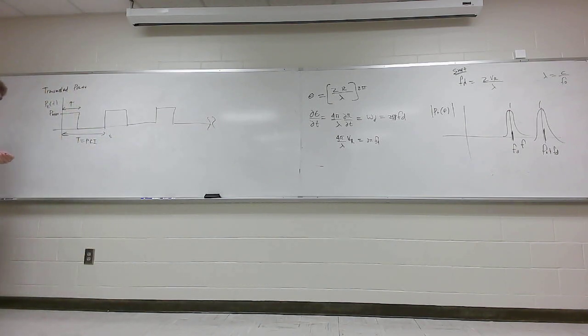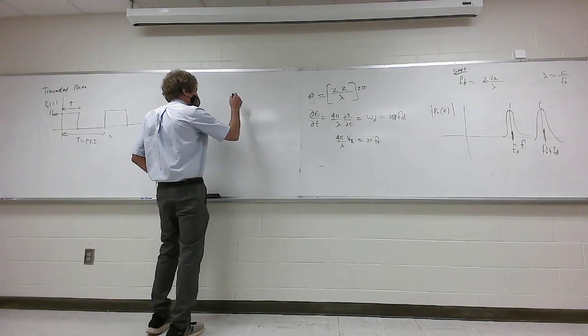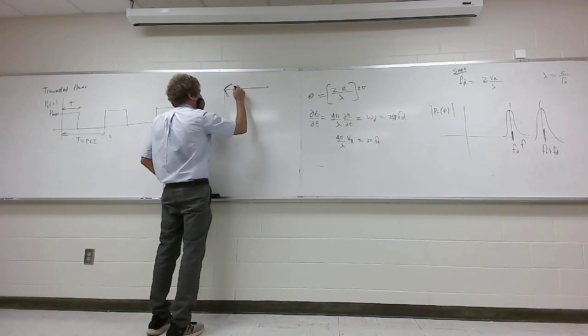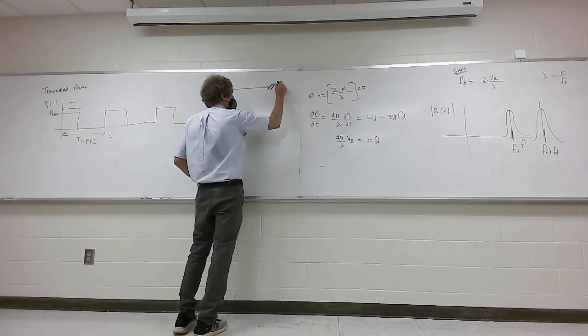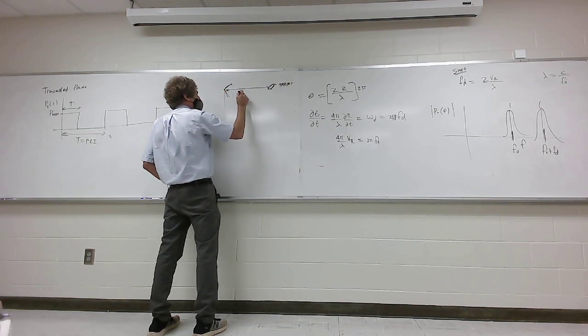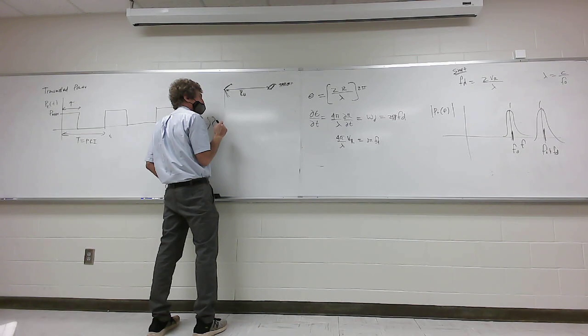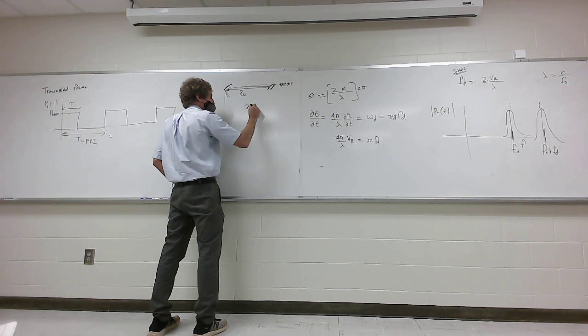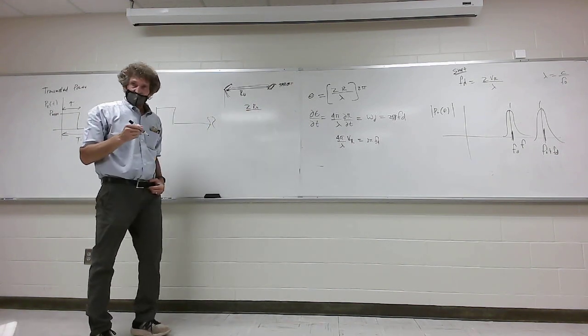Now, there's more to this, but in a nutshell, when we take a look at the maximum distance that we can discern unambiguously, the way we get it is this. Well, this is my radar here, and here's the target. And this we're going to call the maximum unambiguous range. Well, I know the signal goes out and comes back, so it's 2 times R_U would be the distance. Agreed, class?